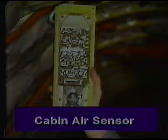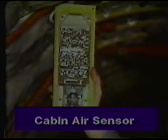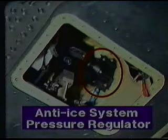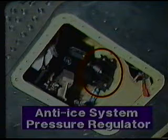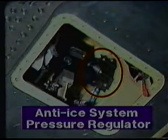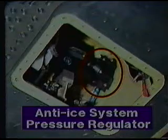The cabin air sensor is also used to provide a signal for the cabin air indicator, so that the pilot may easily determine the temperature of the passenger cabin. The valves and components that prevent the turbine and water separator from freezing are referred to as the turbine anti-ice system. The unit mounted on the wing rib is the turbine anti-ice system pressure regulator.